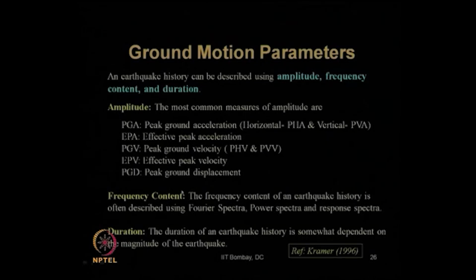Because when displacement is occurring, we are really concerned about what is the maximum value of the ground displacement. Engineers should use their design concept based on the peak ground displacement which is occurring, not that effective ground displacement. There is no such effective. So, that is why that terminology is not present over here. You can see from this slide.